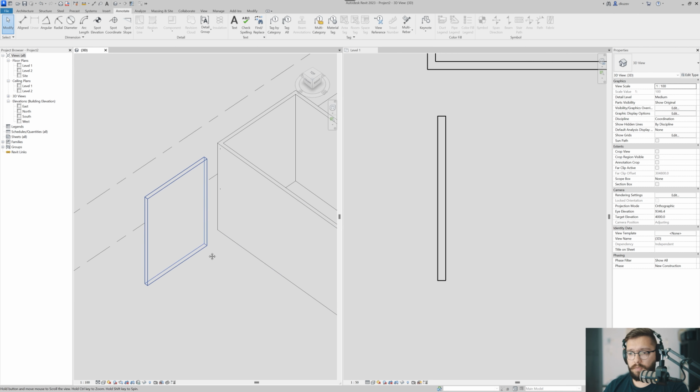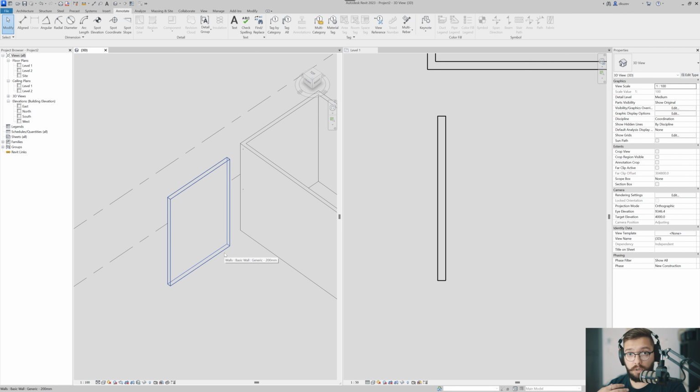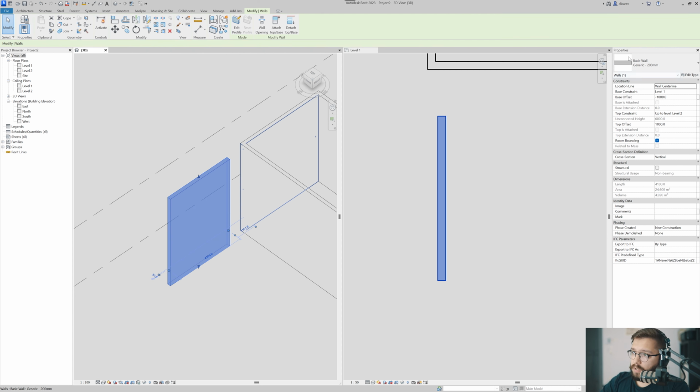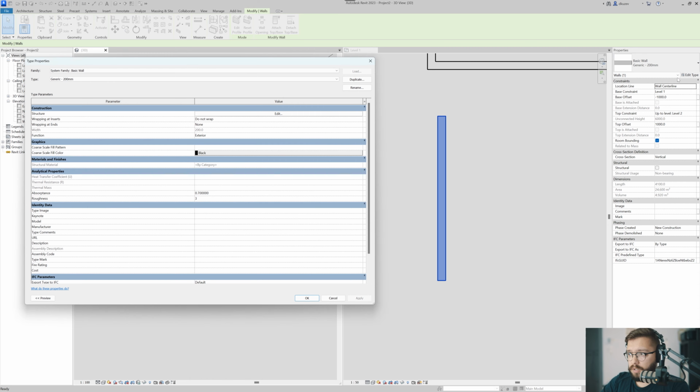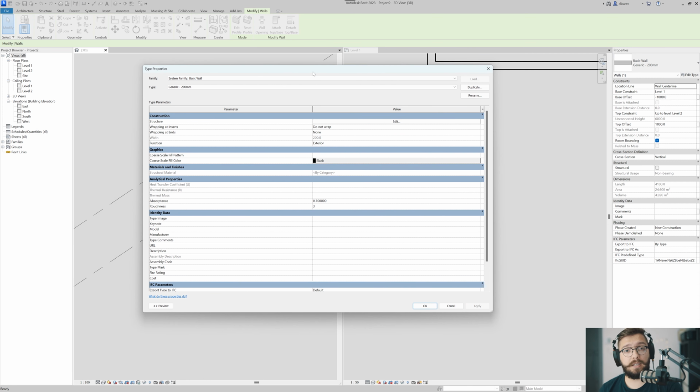Now, the way you modify a wall, or talk about all of its compositions or some of the extra stuff we're going to see a little bit later on, is by selecting it and going to the properties at the top where it says Edit Type. Okay, so this is where, if you click it, we would create a completely new type of wall. And then we're going to start building parameters into it and giving it all the juicy stuff that actually makes a wall in Revit, all right?